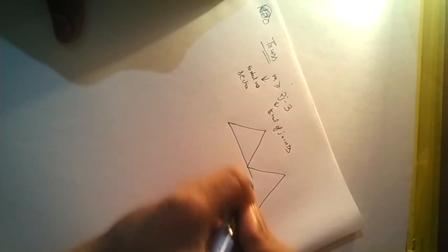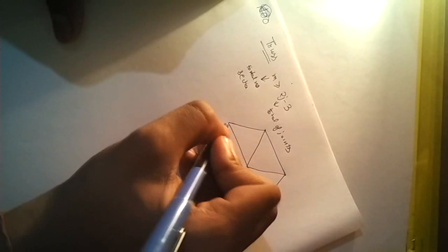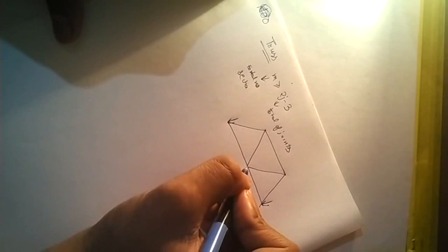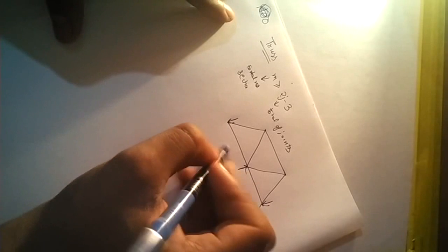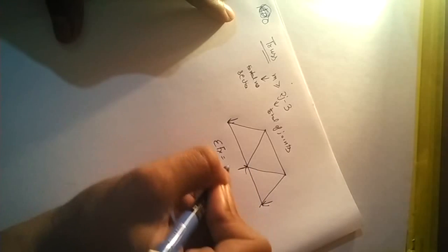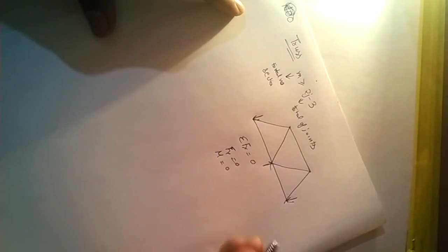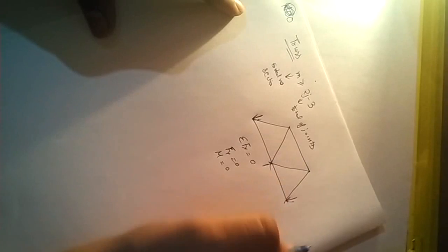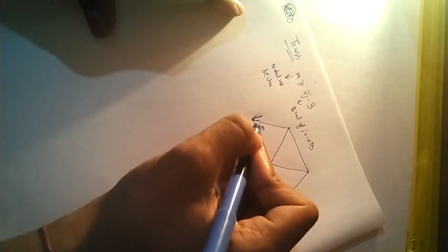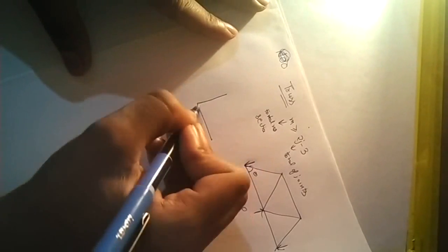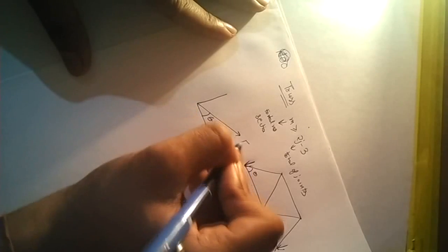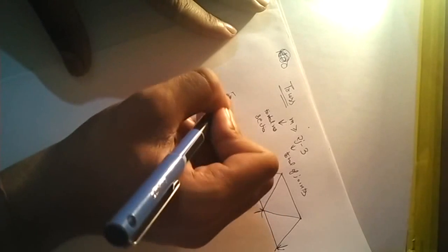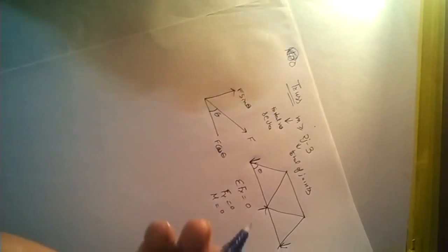These are simple trigonometric questions. If this is a truss given and force is acting here, here, here, the same equilibrium theorem will be applied: Fx equals 0, Fy equals 0, and moment at point O equals 0, and you can easily find out all the loads. Theta will be given. You can divide the force into components, as you know: F cos theta, F sin theta.